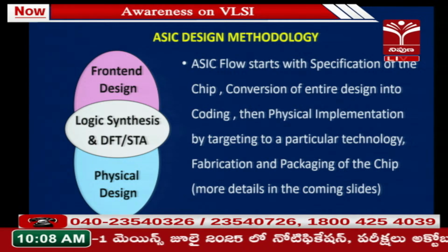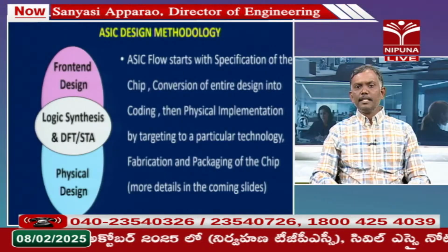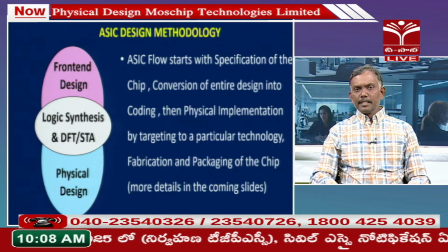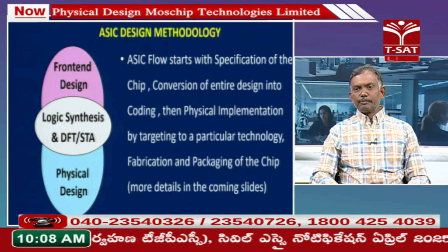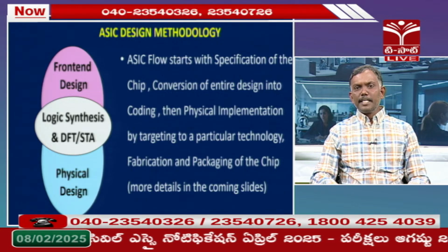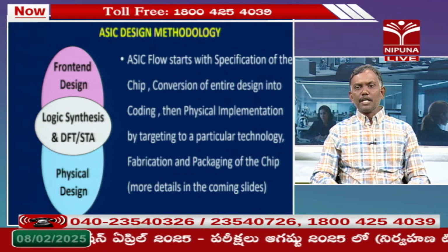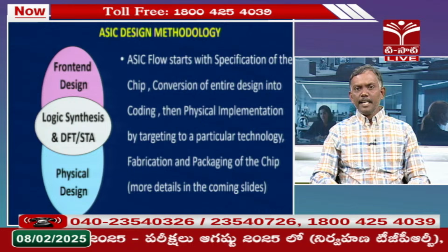ASIC design methodology. Generally this ASIC design methodology starts with specification, then next level is coding and verification, then physical implementation and fabrication and packaging. Of course, we can see more details in the coming slides. ASIC design methodology generally consists of front end design, that is one part, and logic synthesis, DFT and STA, and physical design.